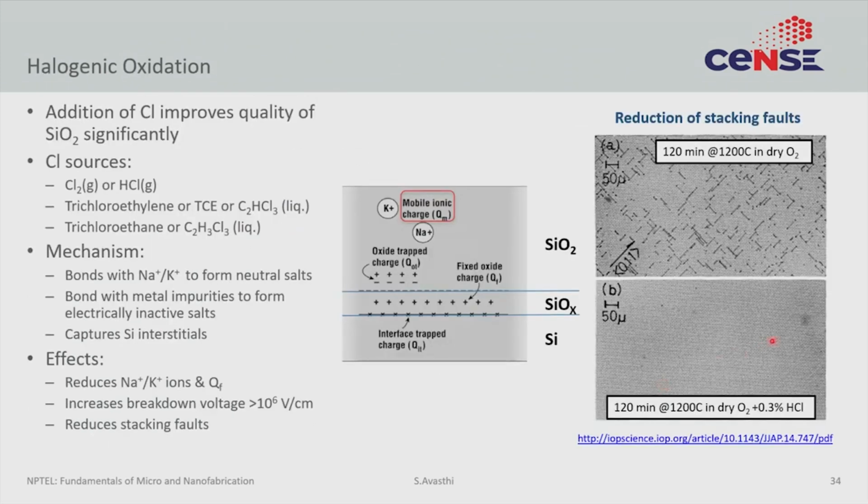Let's talk a little bit about this mobile ionic charge and how to remove that. So part of the solution is to maintain cleanliness. We have already discussed surface cleaning techniques, using CMOS grade chemicals, using clean rooms, never touching the wafers with hands, etc., etc.